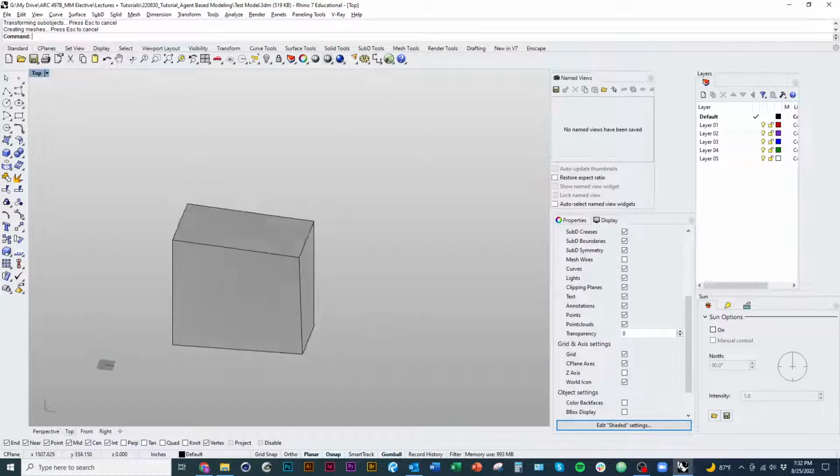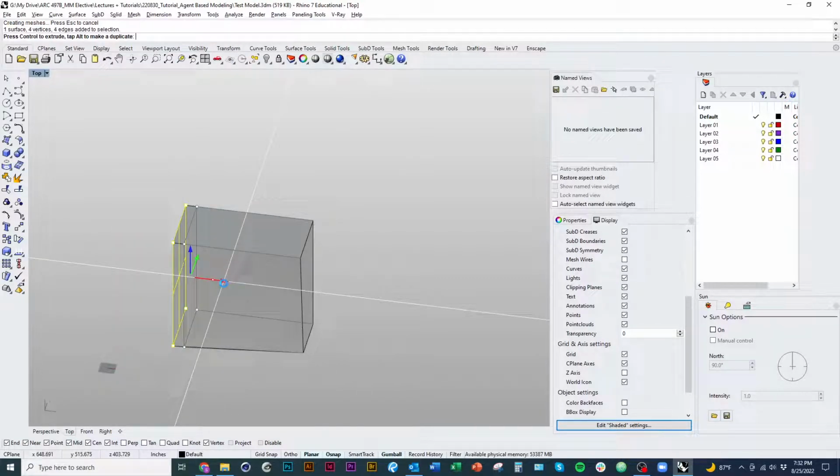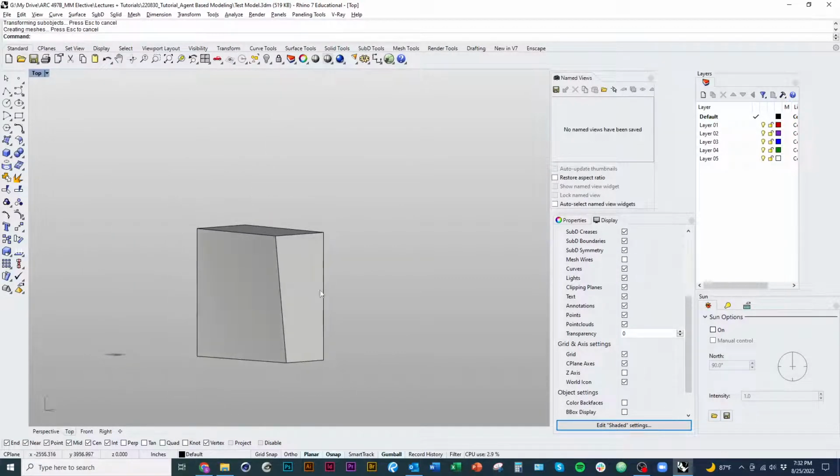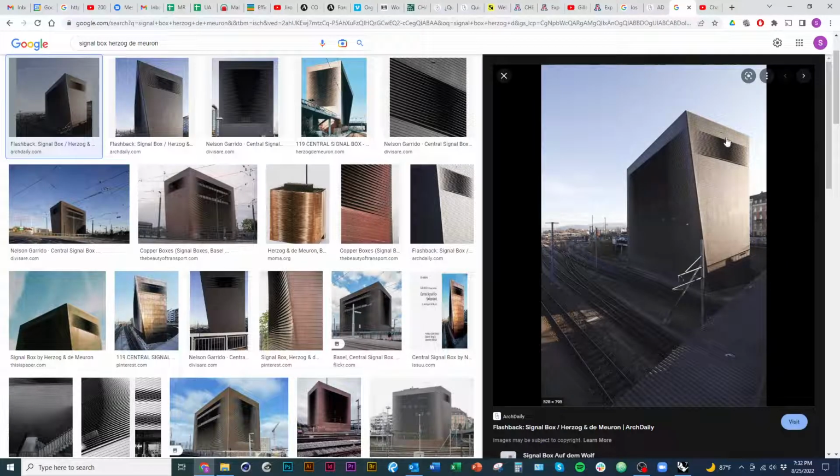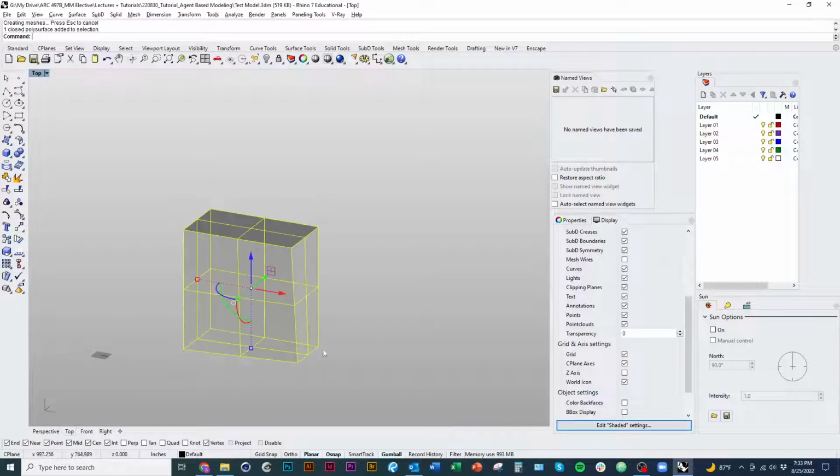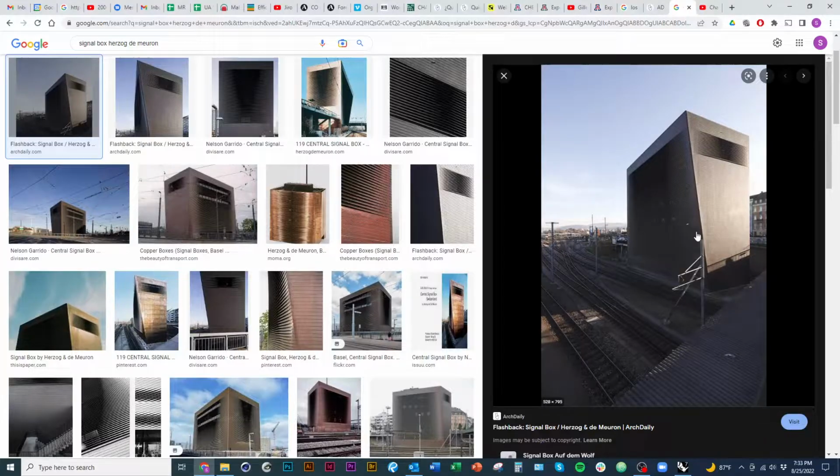The other thing that we want to do, I think, is trim away the surfaces into the segments that we actually have twisting on, so we're just working with the parts that are twisting. First thing I'll do is explode this polysurface into individual faces.